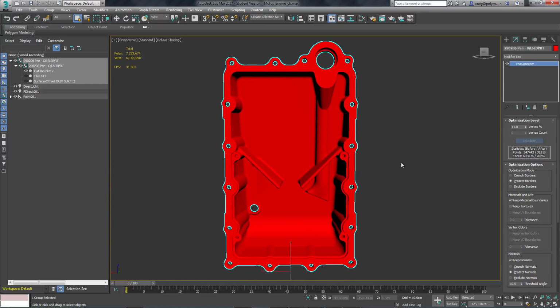Now we need to think about this as one piece versus thousands of pieces. To do this one by one over a lot of pieces, that is something to consider for this conversion process. So batch working with decimation is the way to go. The other challenge here, just the last note on this, is that you want to make sure that you're decimating things in a way that it's preserving that accuracy, but also the parts beside it, that the accuracy is there as well. So you do have a bit of a challenge in preserving that accuracy and decimating or lowering things down in a way that actually balances out and represents the CAD design properly.